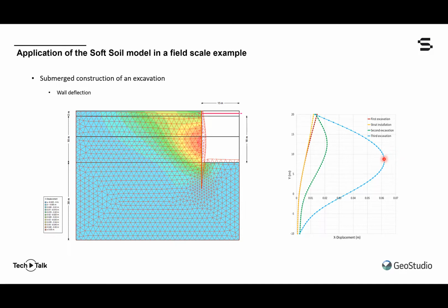And so the deformed mesh of the model, as well as the X displacement contours, which are shown here, indicate that the maximum final deflection occurs just about or just below the mid height of the wall. So here's the exposed portion of the wall, and that would be below mid height. And again, that's confirmed by the coordinate of the maximum deflection over in Draw Graph. So again, we can see the radiating X displacements around that point of maximum deflection.